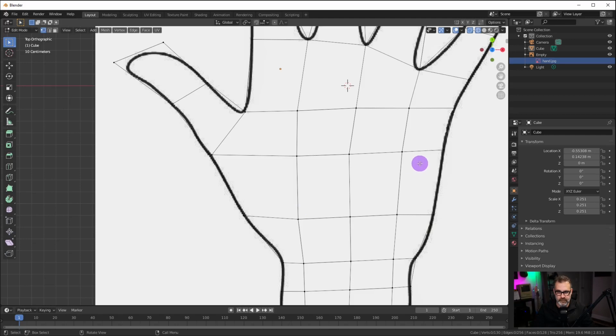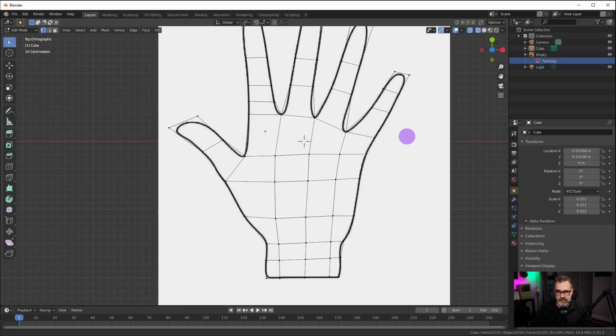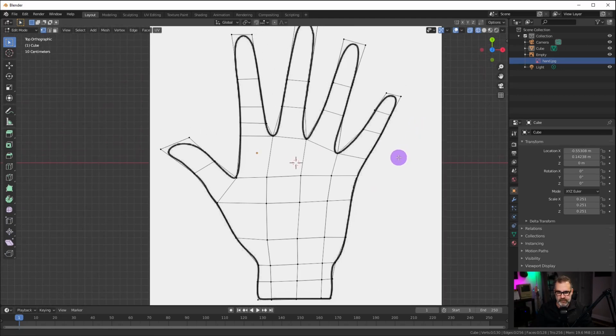Okay? And if I want to fix things up just a little bit over here, double press A, just always ensure that you're deselected, box select, and G key for grab. Okay, that's good enough. Okay, I'll zoom out just simply by using the wheel of the mouse and just bring things down a little bit.